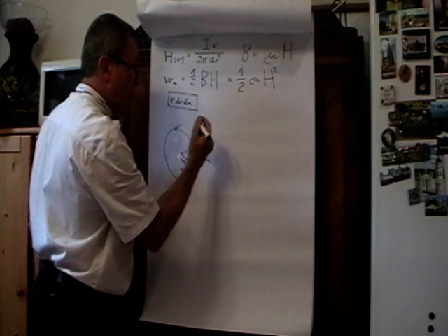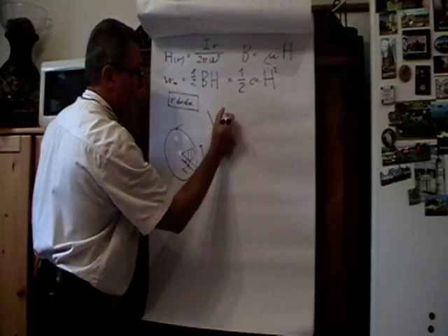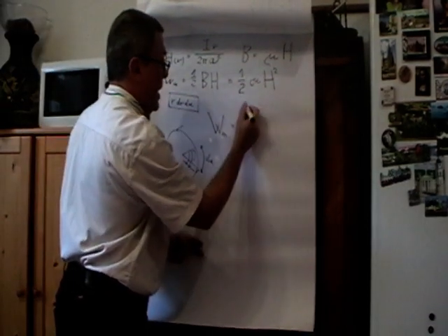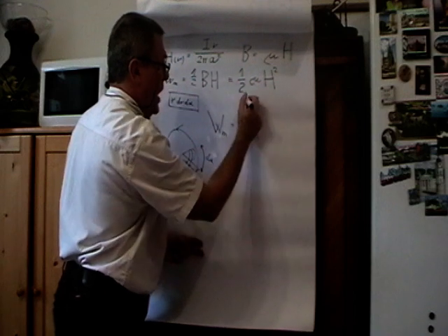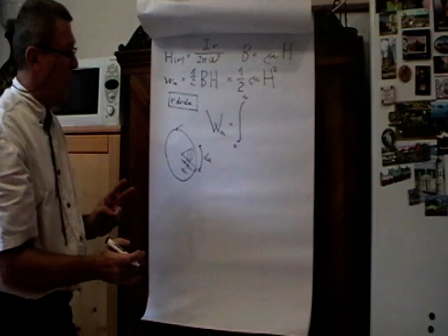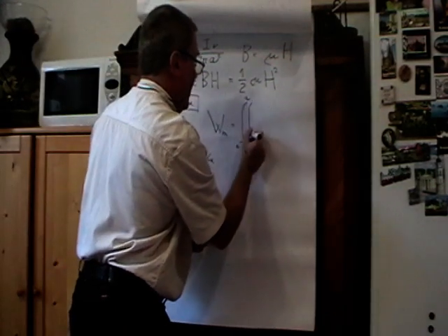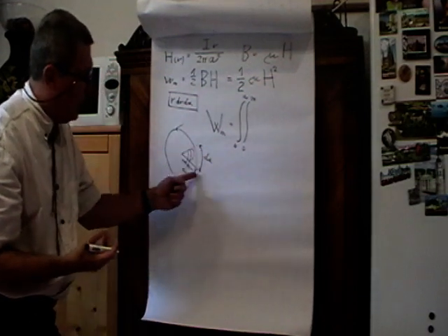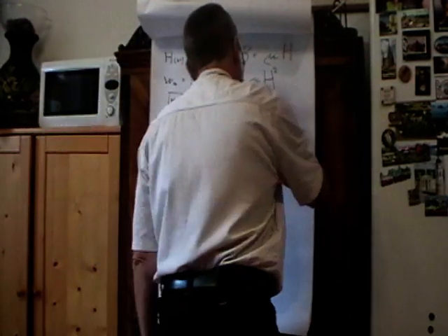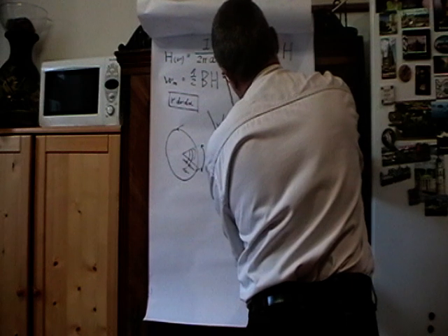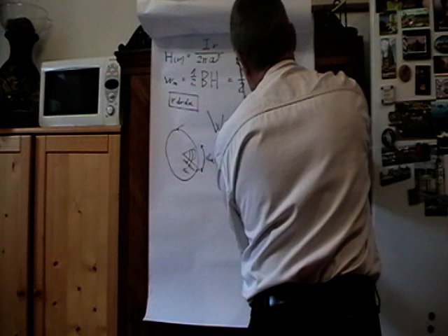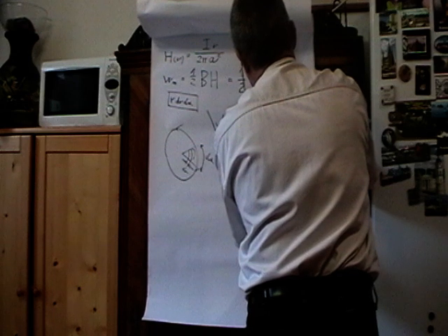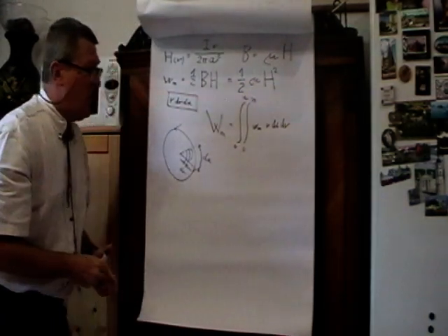So we would have the total energy, this big W, the magnetic energy in 1 meter of the wire, and it would be an integral from 0 to a, which is the radius of the conductor, an integral from 0 to 2 pi, which integration is done according to the alpha, of the magnetic energy density, small wm, times the element, which is r, okay, interchange d alpha, dr. So this is the integration we should carry out.